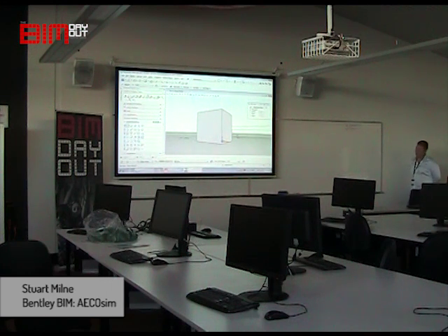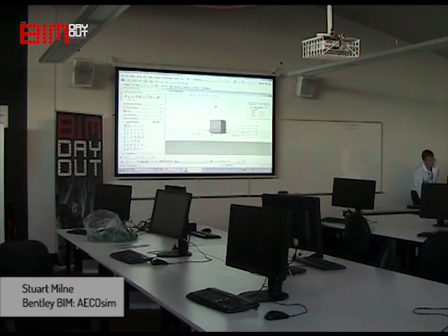But for the purposes of what we're going to do today, we can stick with a parallel working view. It's probably the easiest to work with. So to get back to our parallel view, come up here to the tool that gave you view perspective. You can hold that down and say camera off. You're back into a parallel view.